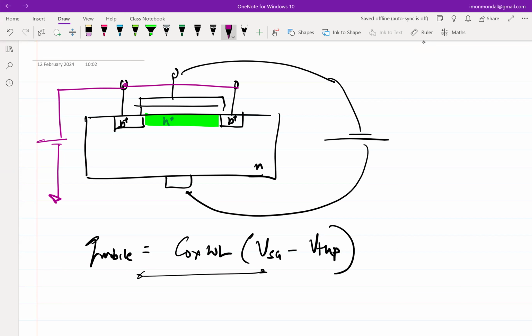So the pentavalent impurities got rid of their electrons, so essentially we had Nd plus. Forget about the D part; D is because we call it the donor, but the key thing is that we have positive fixed impurities there. So why does this expression allude to only mobile charges?